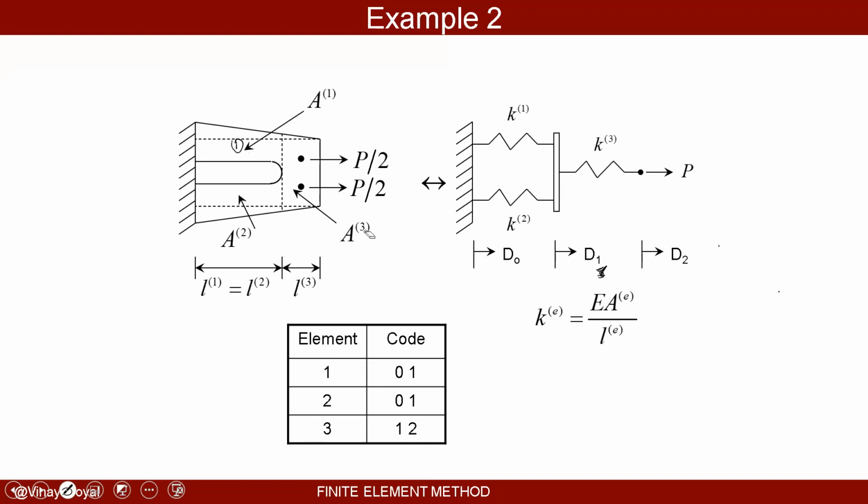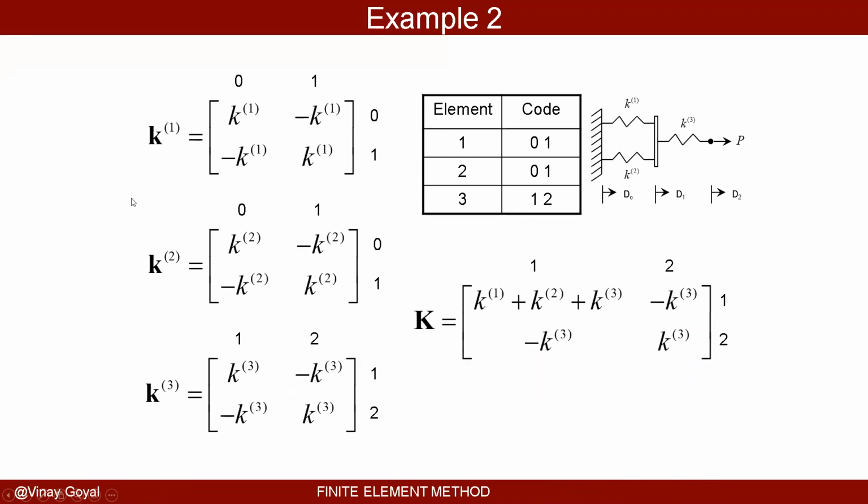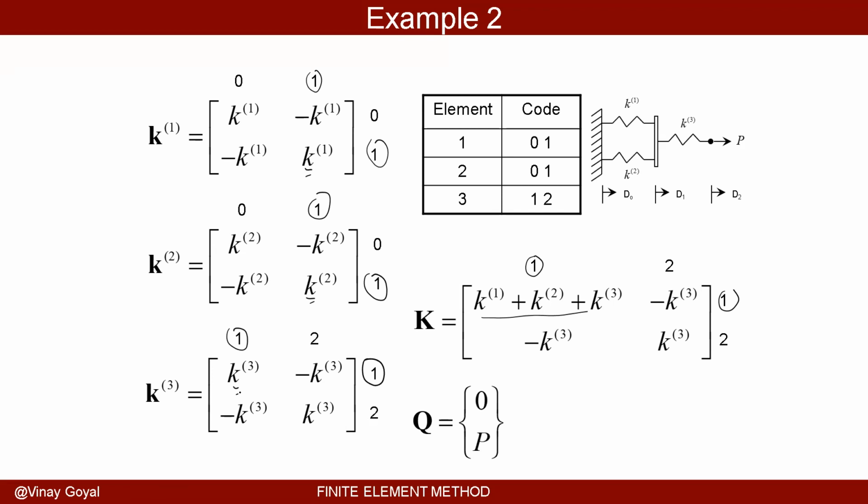Let me clean this up. And I'll again explain the procedure really quickly, but I'm interested in doing, say, 1-1. That's an interesting one because look, 1-1 shows up here, it shows up here, and shows up here. So they have to be all added up, as you can see there. That's that one, that one, that one that has to be added up. So you have to basically search for these and populate it. In our case, there's no load applied here. There's a load applied on this end, which is P, and I put it there.